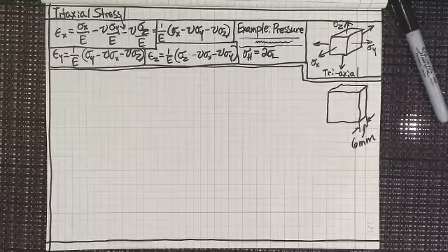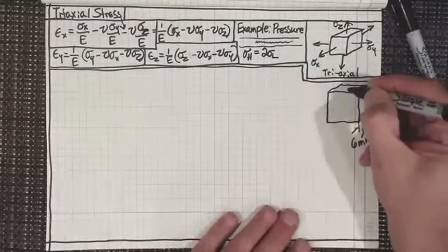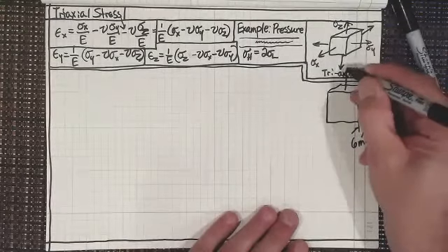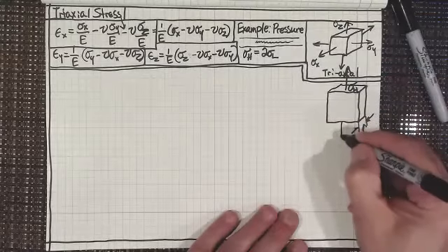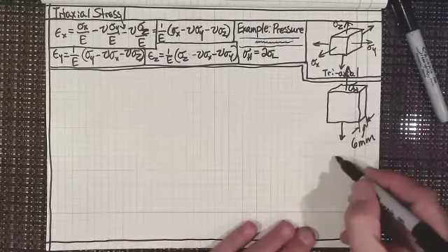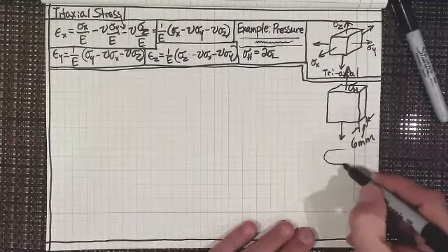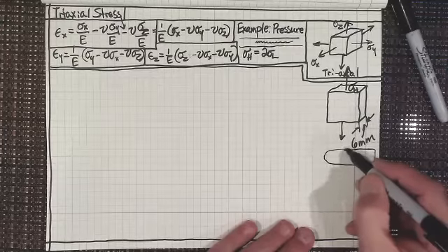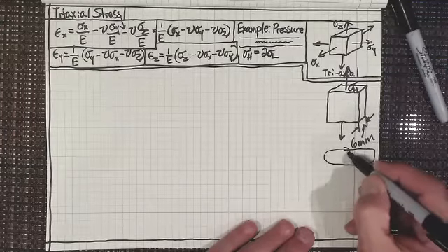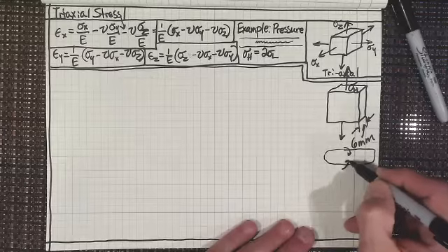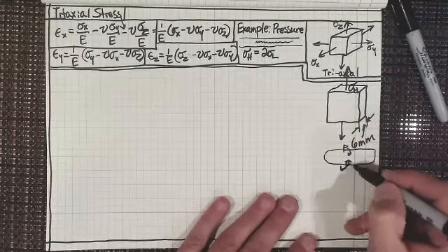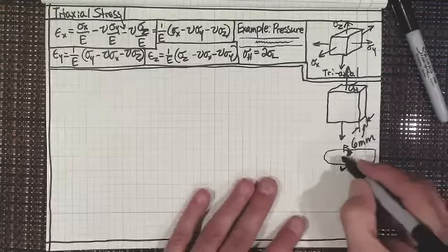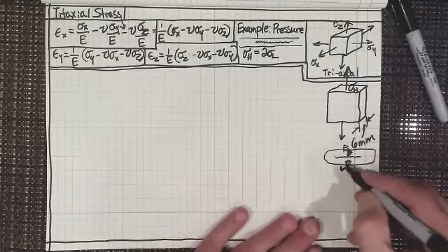That's not what we're really here to see, though. If I draw this, what I want to do is draw the hoop stress. Now, the hoop stress is in the y direction. And why do I say that? Because when you look at the pressure vessel, the hoop stress is what's coming around in this direction. It should be going in that direction, actually, because it's ripping it apart, so that it has like a rip along there. So that's the hoop stress.